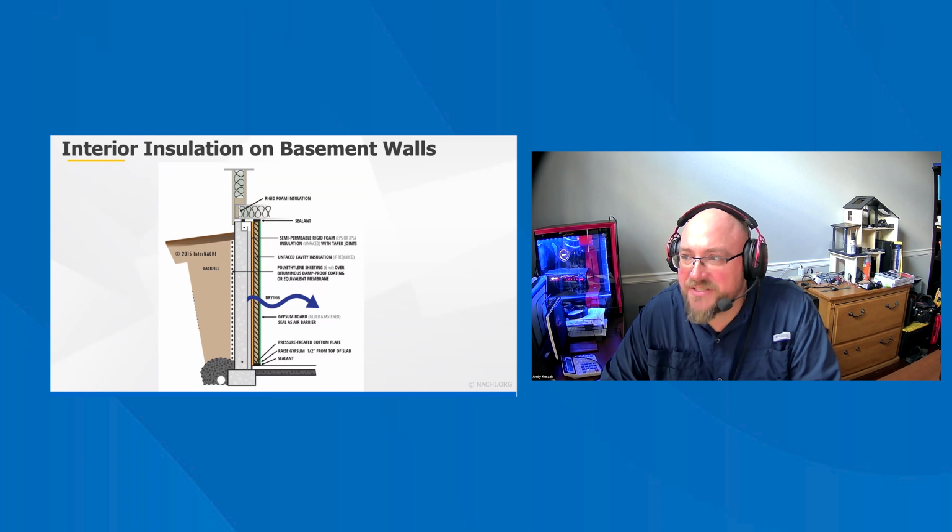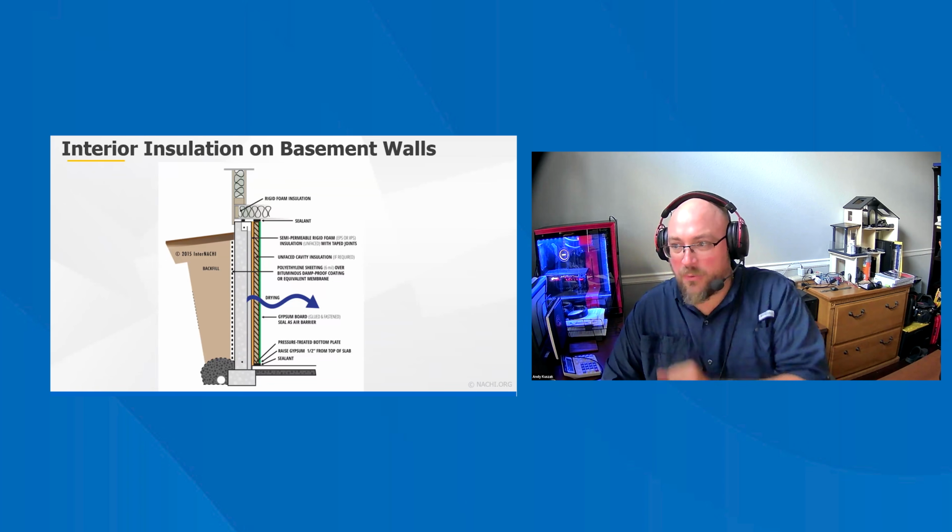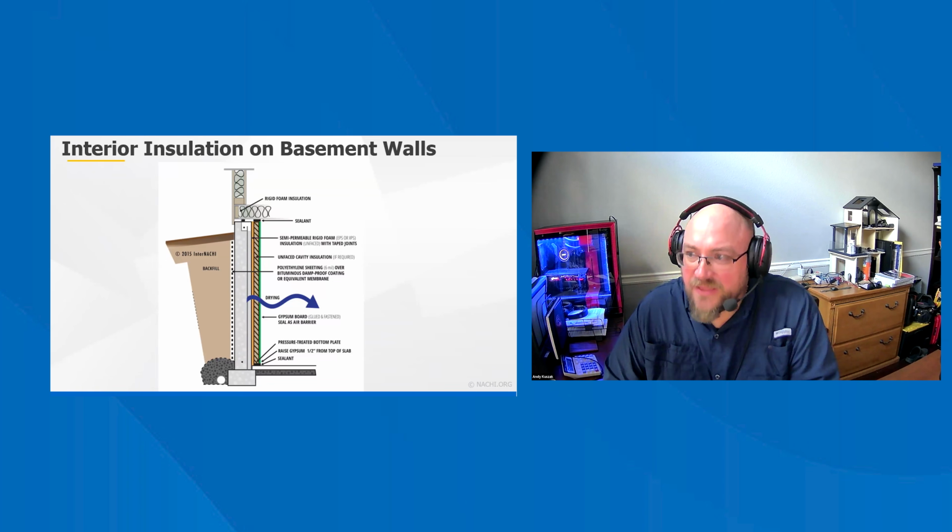Traditional practices, such as the use of a warm-in-winter vapor diffusion retarder on the inside of the finished wall system, have resulted in moisture problems. Low permeability and continuous vapor diffusion retarders, such as polyethylene sheeting and vinyl wallpaper on the interior side of the basement finishes, should be avoided because they will trap moisture vapor moving through the foundation wall. They will also slow the drying process for newly formed foundation.